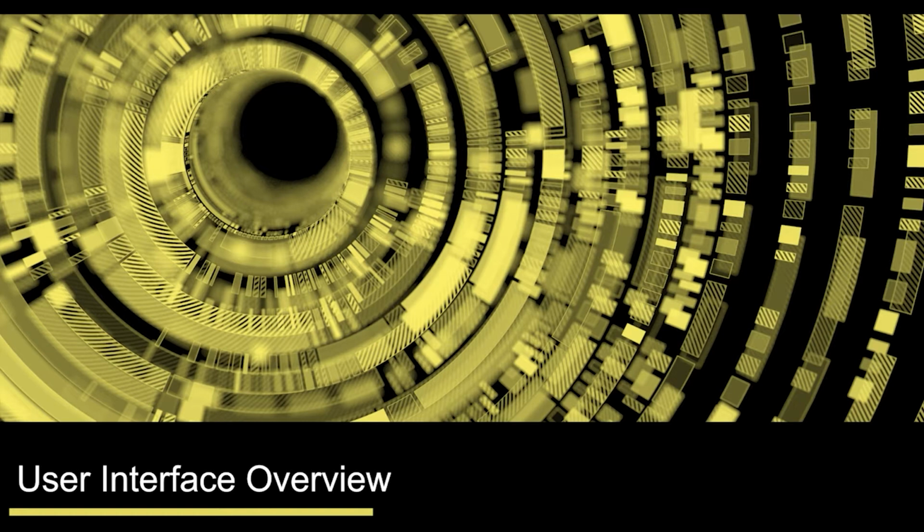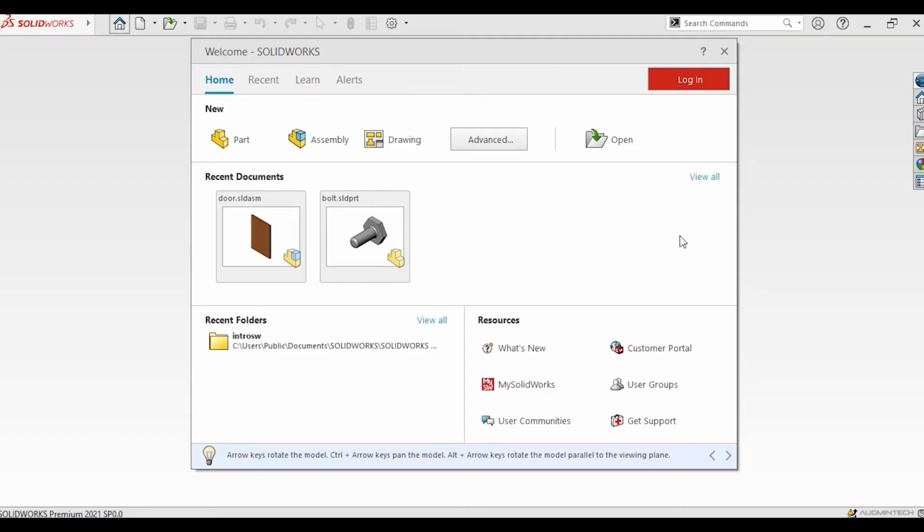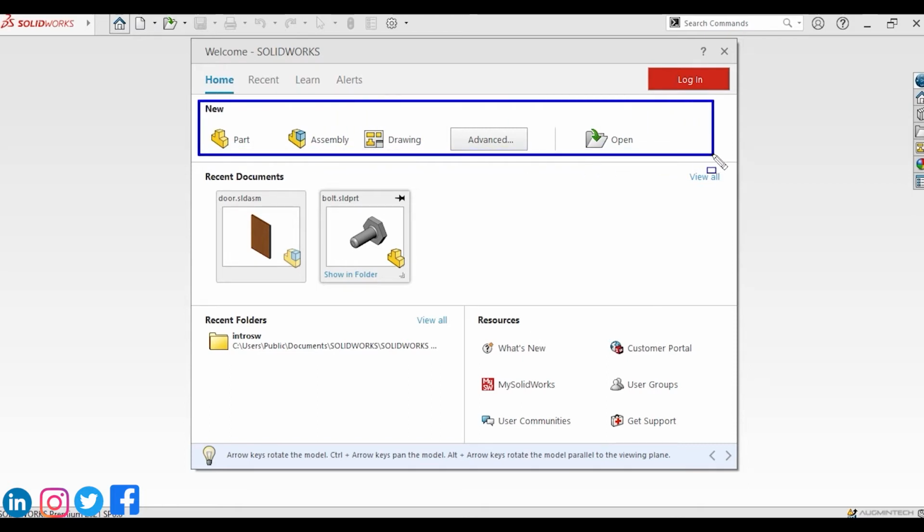In this session, we will learn about the overview of SolidWorks interface. So let's start. When you open your SolidWorks, you will find a welcome dialog box over here. This welcome dialog box is divided in several different sections. These sections are new. By going in new, you can find your new part design, new assembly design and new drawing. Let's take a look at what is part, what is assembly and what is drawing.